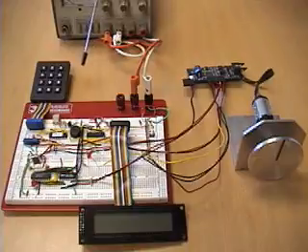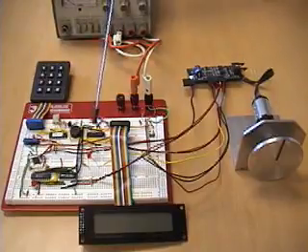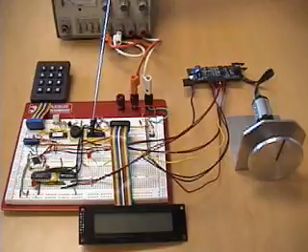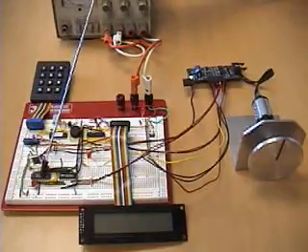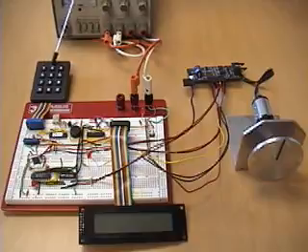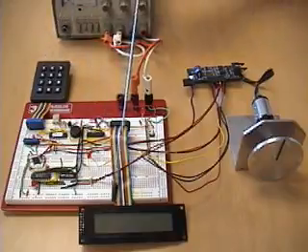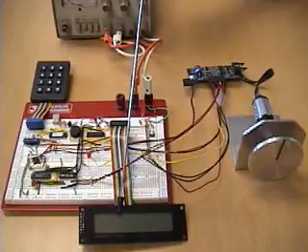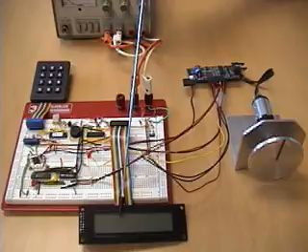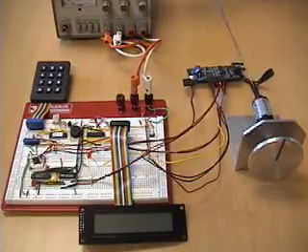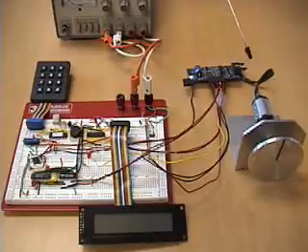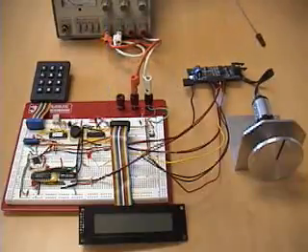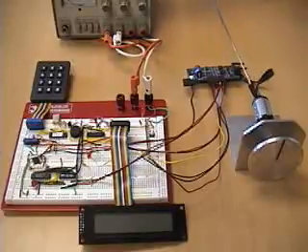This is an experiment to demonstrate position and speed control of the DC motor. There are two microcontrollers. This is a 16F88 and this is a 16F84. A keyboard is used to input data, and an LCD display displays the data that's input and also provides information as a user interface. The motor, DC motor, is driven by an HCTL bridge, which is interfaced to the microcontrollers. And the motor has an encoder and a planetary drive attached to it.